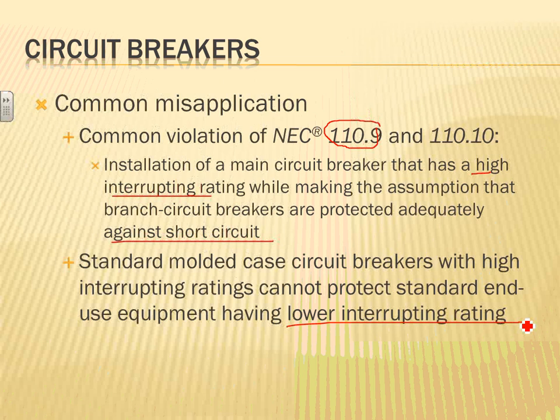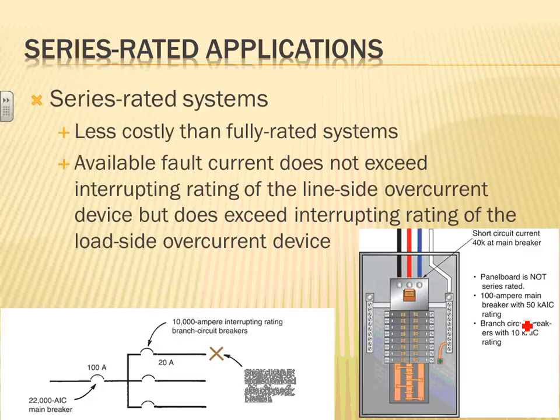So that's where fuses and current limiting fuses become a very big advantage. Every time you have soft starts or electronic equipment, they call them power electronics, like soft start VFDs in the system, fuses become an advantage, and sometimes the manufacturers actually fuse them at a certain value to protect them. So be aware every time you have power electronics in the circuit. Make sure that they have either a withstand rating by themselves or in conjunction with a fuse. That will lead us to the series rated.